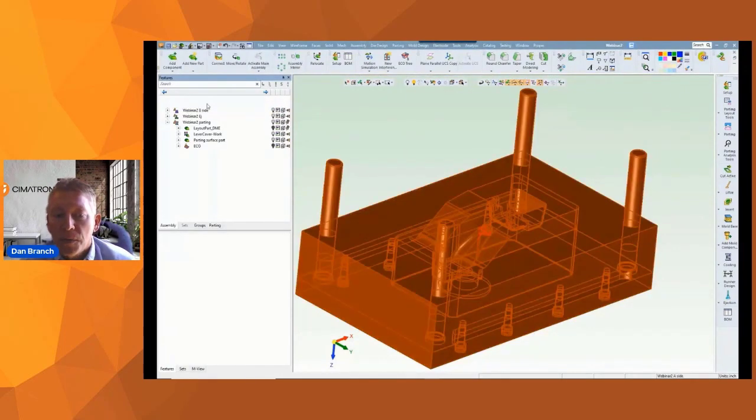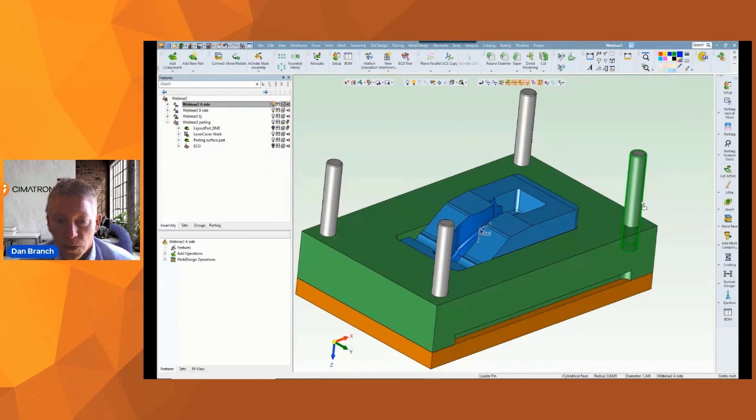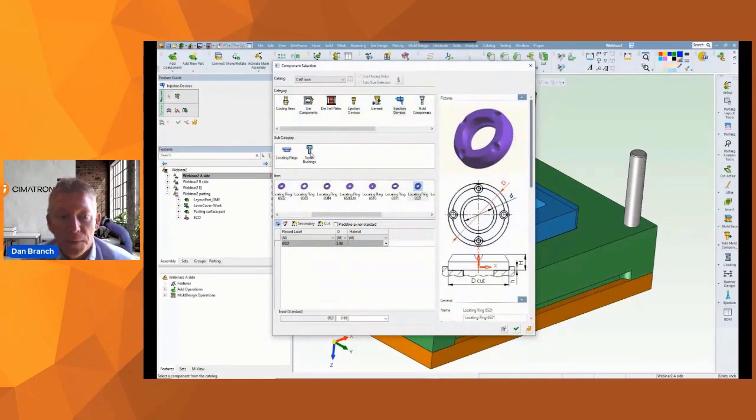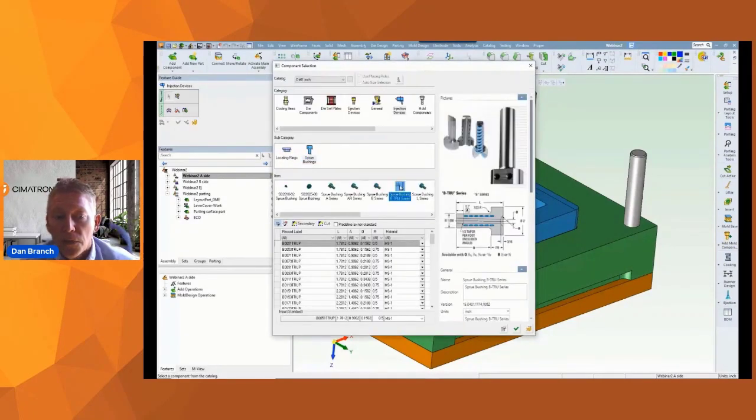Cimatron has some nice dedicated screens for adding mold components. These help you find the right part and provide automated rules for placing it. One category is for injection components, and it's in here that I find the DME conformal cooled sprue bushings. There are a lot of sizes to that part, but I can filter some off. For example, I only want to see the bushings with a 3/4 inch radius. And I'll need the longest one available to reach through this deep cavity block.